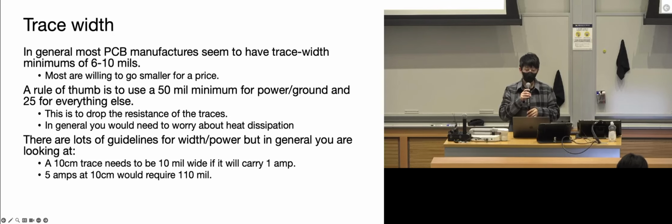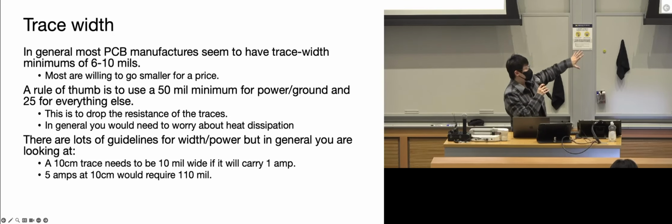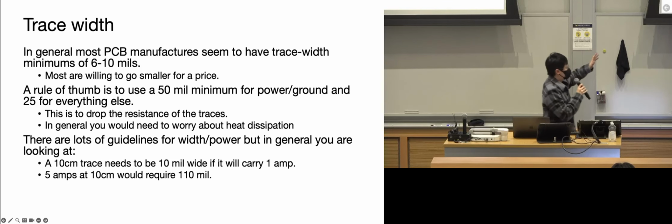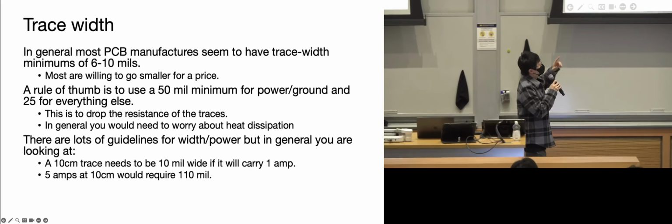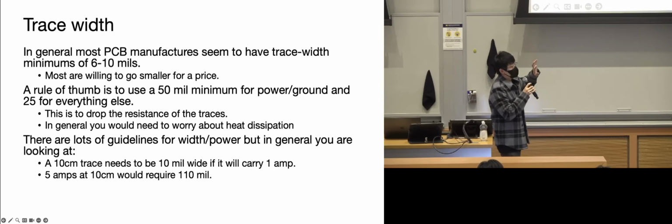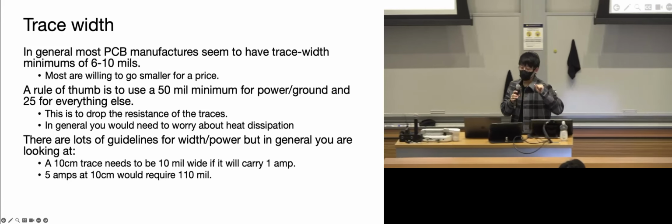But generally, as a reference, if you have a 10 centimeter trace, not sure why you would have that, it's quite long actually, but if you do, it needs to be 10 mils wide if it needs to carry about 1 amp of current.